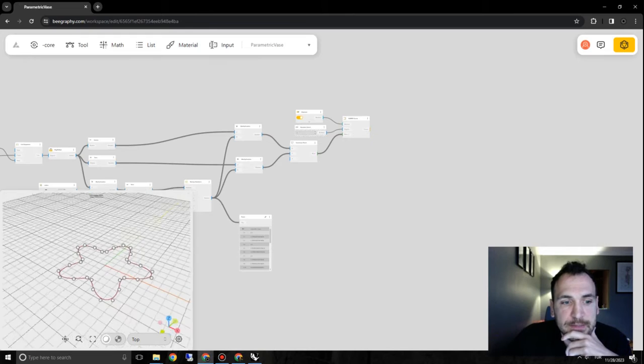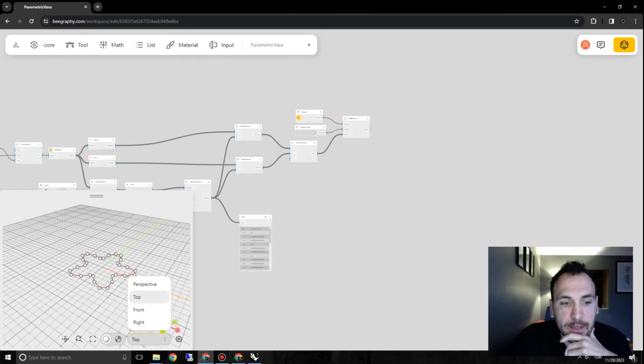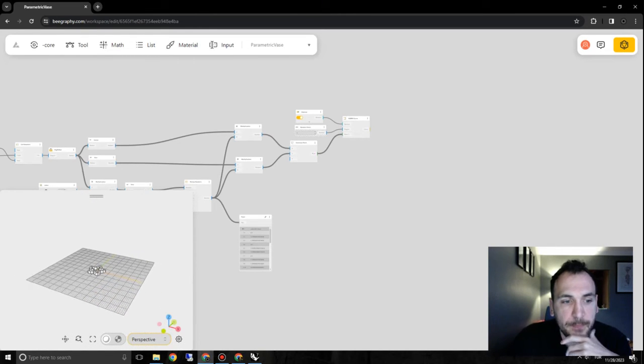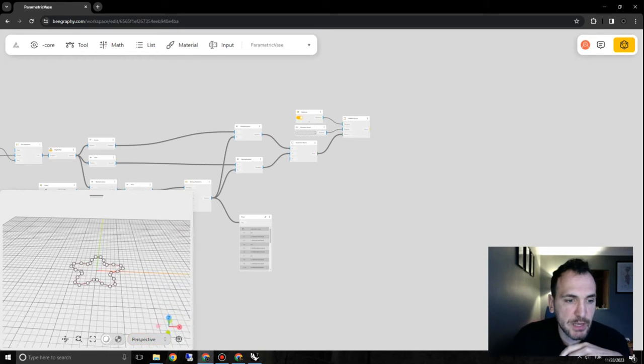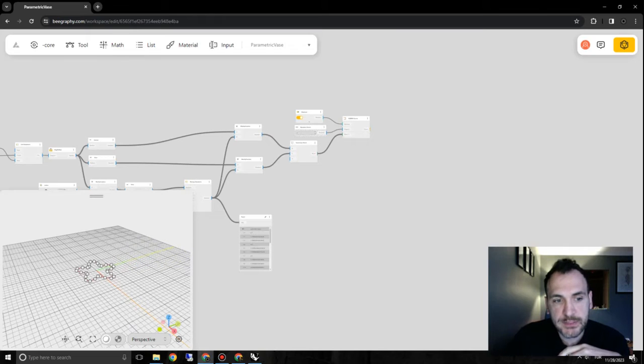Now, the next step is to work in 3D, and basically we want to make a series of these operations, right? So I want to make copies of these profiles so that we can create maybe some sort of a loft. So I'm going to start by making points where this profile could be translated to.